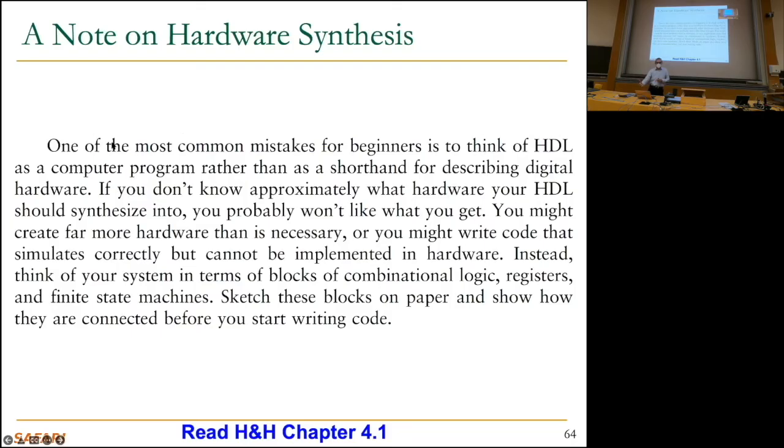And I agree with this actually, wholeheartedly. One of the most common mistakes for beginners is to think of HDL as a computer program rather than a shorthand for describing digital hardware. If you don't know approximately what hardware your HDL should synthesize into, you probably won't like what you get, especially if you have stringent requirements.